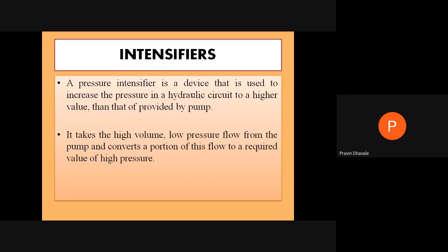At that time, in order to increase the pressure of that fluid, we use certain pressure intensifying devices called an intensifier. Means an intensifier is a device that is used to increase the pressure in a hydraulic circuit to a value that is greater than the pressure developed by the pump.